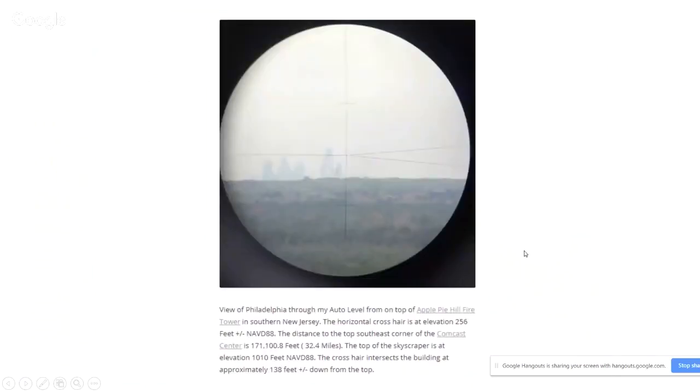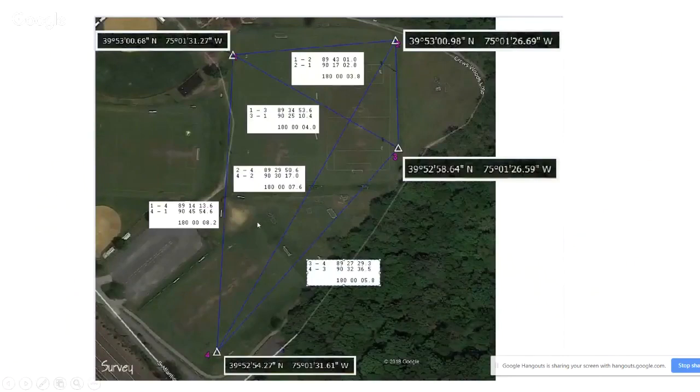Now, here's the short test. I'm going to probably bail out of this now. So here's this little park I have. These distances are hundreds of feet, and I have reciprocal zenith angles measured. I've done this a number of times. I just did it on this triangle right here, setting the instruments and the targets level with each other. That's just another interesting aspect. I did that a week ago, so that data is in the can, ready for another video.